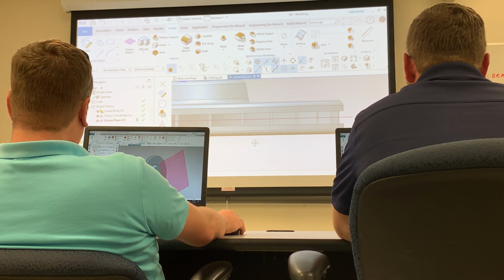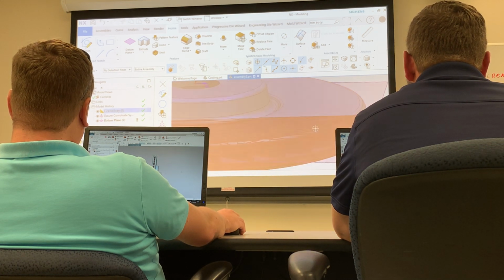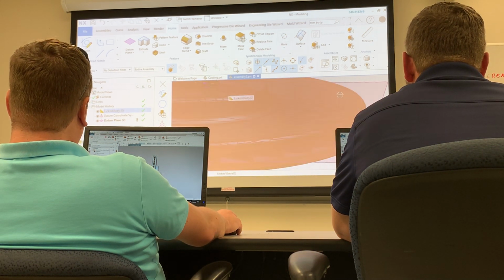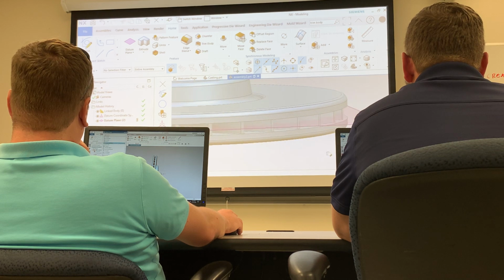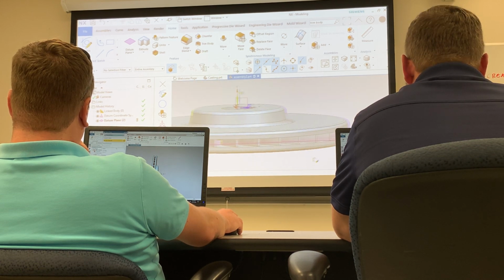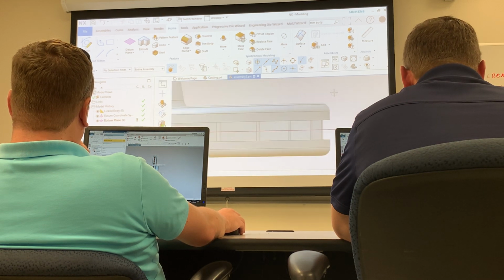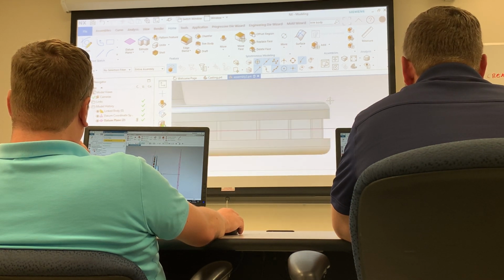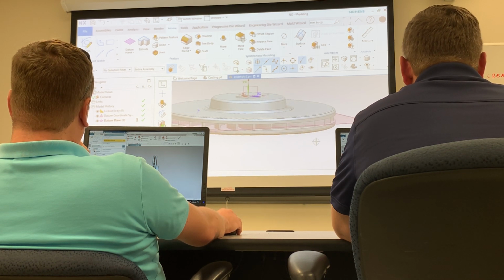Based on what you know, how could you go into this model at this point and trim off those surfaces? Machine a layer off of the top, machine a layer off of the sides of the rotor. Any suggestions for removing that material? Do subtract? Could do some quick. Yeah, so you could subtract.